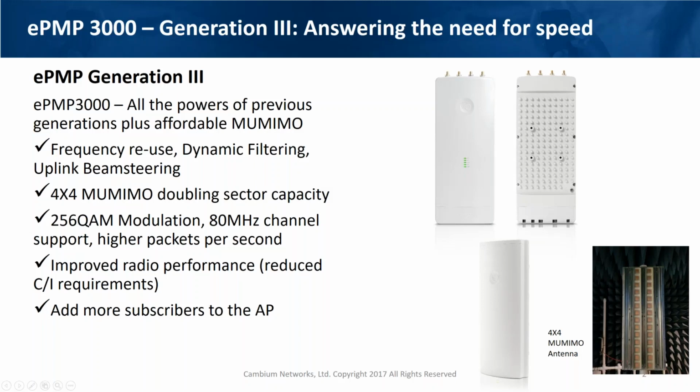But in 11AC, you had two flavors, and that's partly because there were so many things added in the 11AC spec that most chip vendors in the ecosystem that makes your home routers and enterprise Wi-Fi's could not pack all those features into the single release of a chipset. Thus, the concept of a Wave 1 and Wave 2 was introduced.